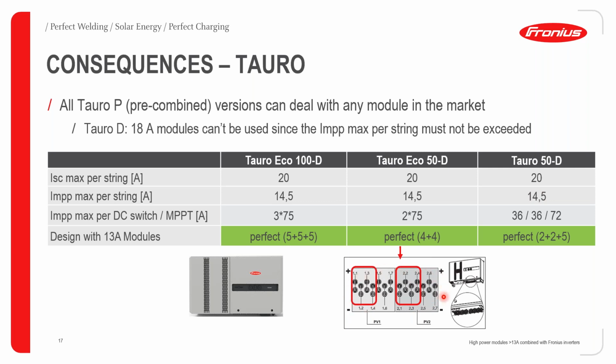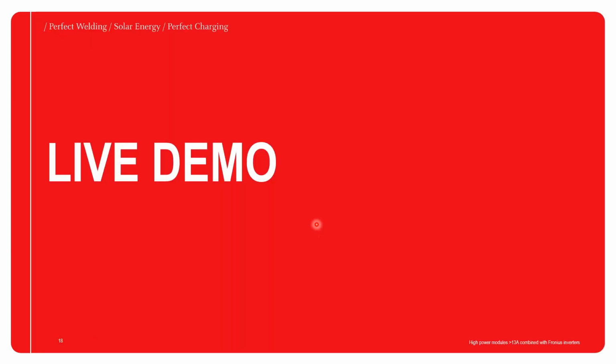These are going to be provided with MC4 plugs, which is quite different from the Snap inverters, whereby you need to connect the strings directly to the terminal block area of the Snap inverter. So the connection of strings directly to the Tauro is going to be quite fast and easy in comparison.